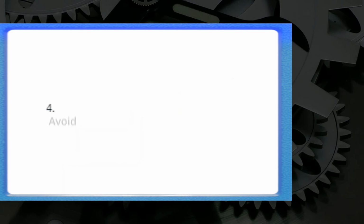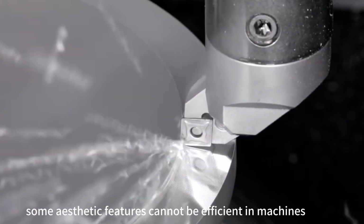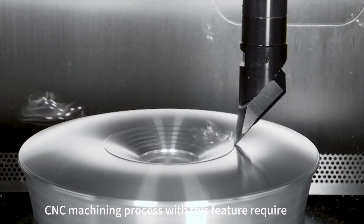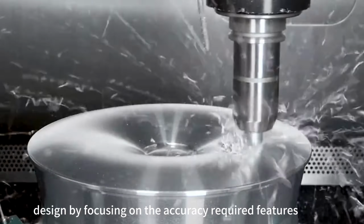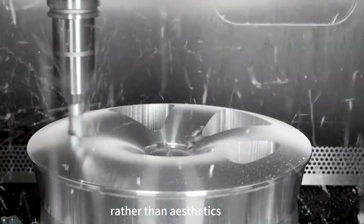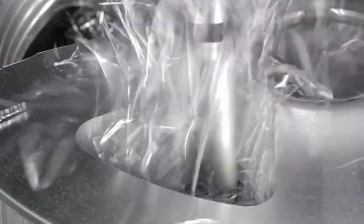4. Avoid unnecessary aesthetic features. Some aesthetic features cannot be efficiently machined. As a designer, you should ask yourself what CNC machining process this feature would require. Is it a 5-axis or 3-axis machining process? You can improve your design by focusing on the features that require accuracy. Rather than aesthetics, it is best to use post-machining processes to change aesthetics.